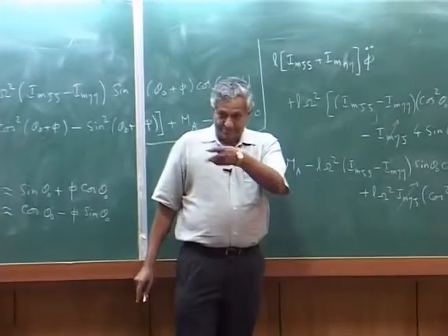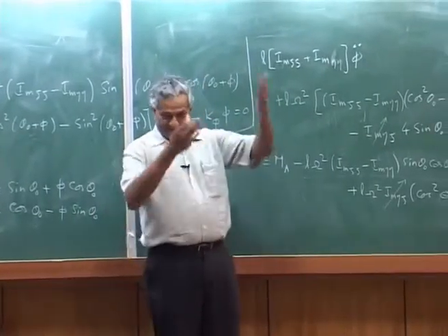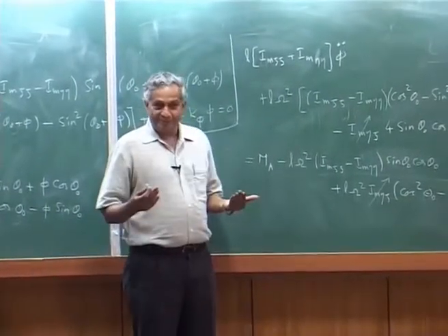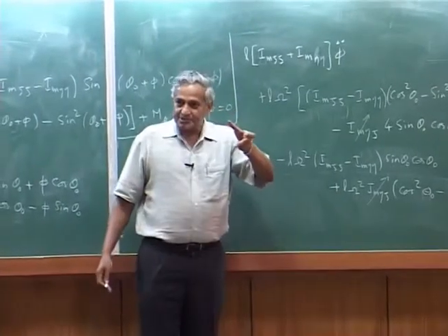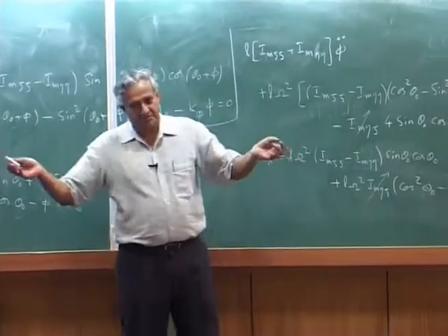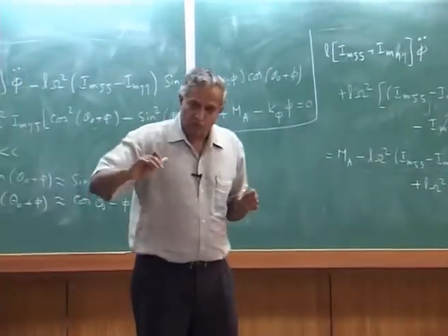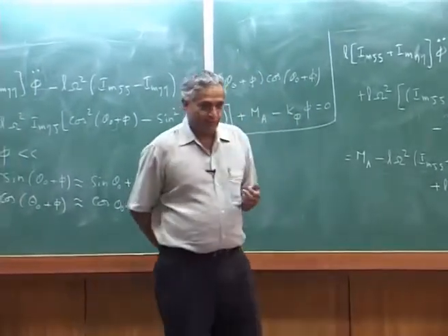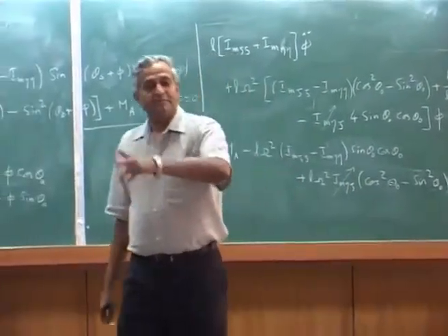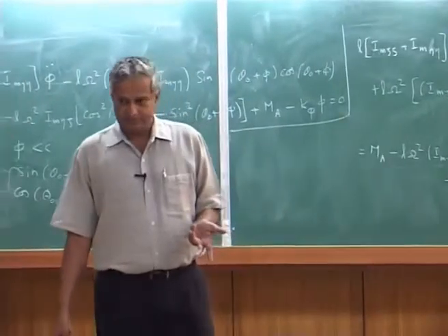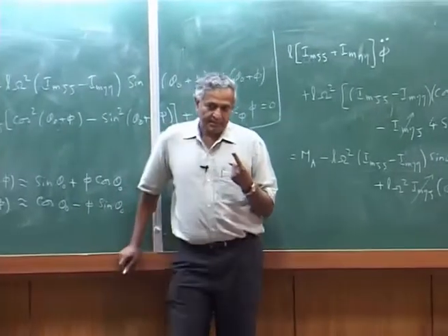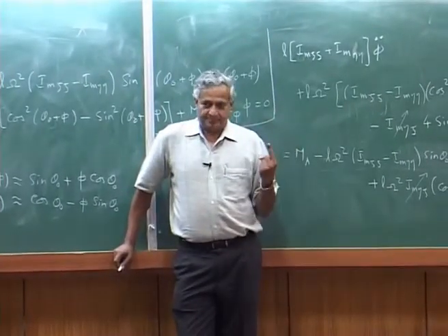Now you see the assignment which I gave. When we rotate it at a higher RPM, okay, you can have an elastic twist of the blade due to control system stiffness plus maybe the blade elastic stiffness. There is a nose down. One can actually reverse calculate what should be the Kp, assuming that this must be my pitch angle. Okay, so usually what you set, pilot may give a command.